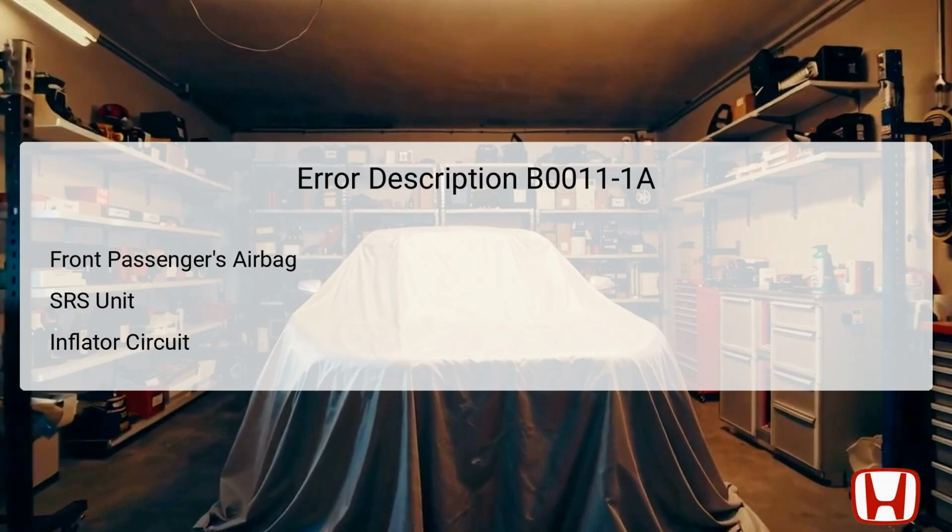If the voltage on the detection line falls below a specified threshold, the SRS unit identifies a malfunction, resulting in the triggering of this diagnostic trouble code. It is essential to inspect the airbag and accompanying wiring for continuity, ensuring that all connections are intact and functioning properly to prevent safety risks.